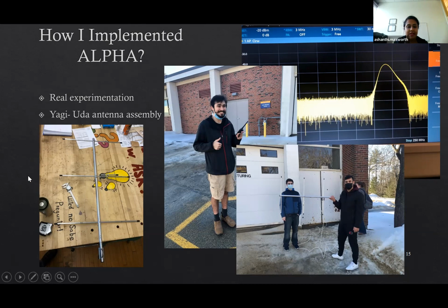These antennas are not radiating in all directions. There's a strong directional beam pattern. Therefore, you have to align it in the right direction, otherwise your TV reception goes away. So these are the Yagi antennas. It's a patented design by two people.